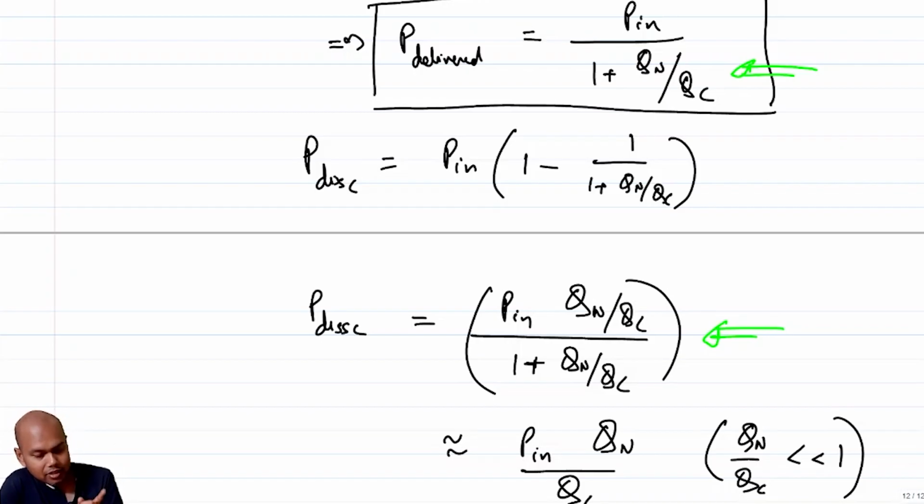By the way, let me correct the statement that I made. One minute back I made the statement that component Q is the same as the network Q. No, that's not the case, right? If you have only one inductor and a resistor and nothing else, even for a simplistic network, they are not the same. You can obviously design networks which have a different network Q than the component Q.